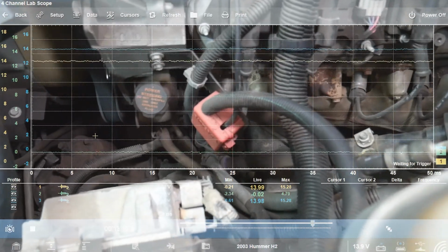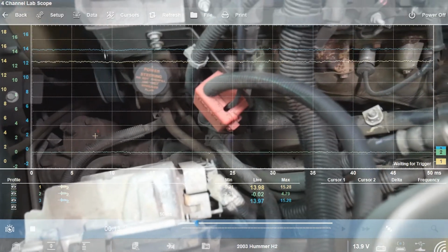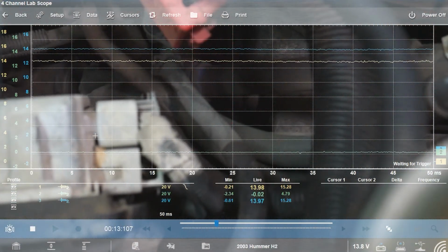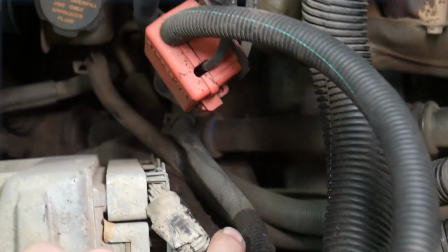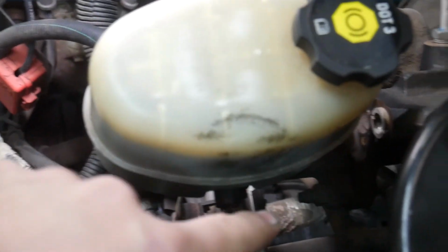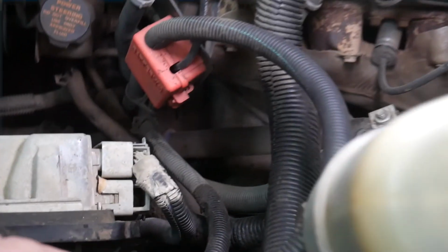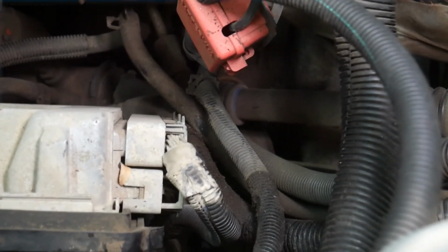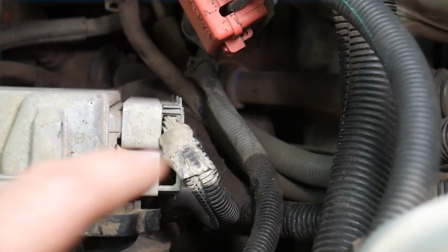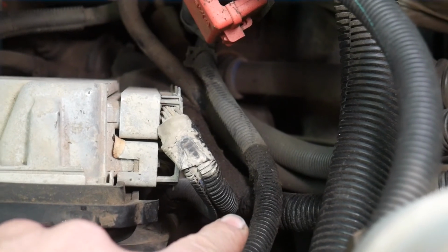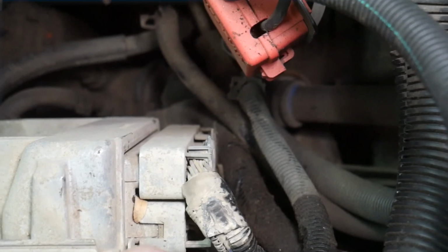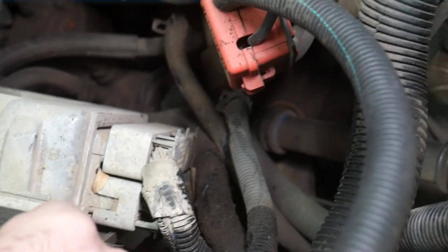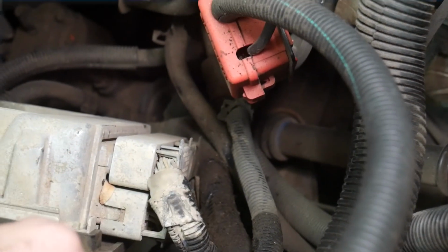Well, I'll show you what I found. And I haven't taken the wiring apart completely here yet. Well, right down here is the power steering line. Goes from the pump up over here to the hydroboost, back there somewhere. So whenever I steer the vehicle, more than likely that line is flexing and moving. Well, it looks like it's leaking a little bit, but it's also right up against the wiring harness coming out of that other PCM connector.